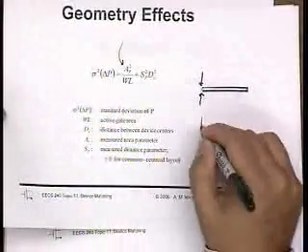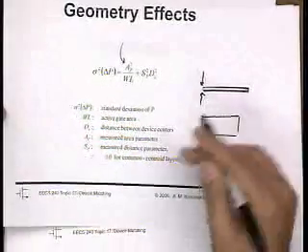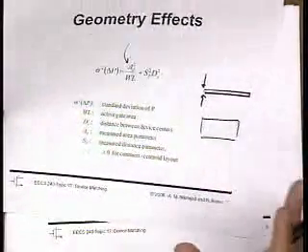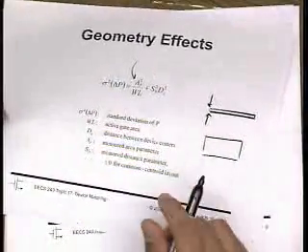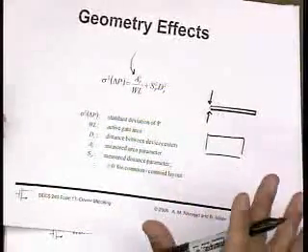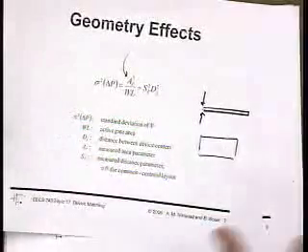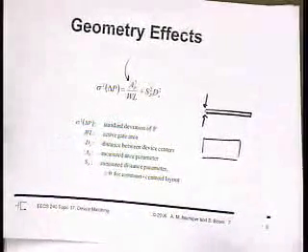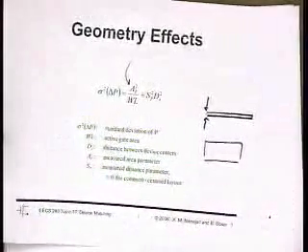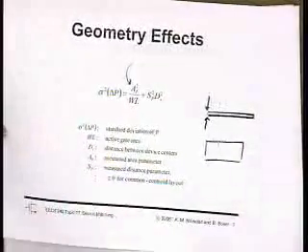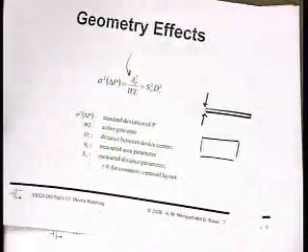The assumption here is that average quantities make sense. If you're talking about a transistor that's so small that a single dopant will make a difference to the threshold voltage, then yeah, this model doesn't work. But usually in analog circuits, we're not dealing with that. In digital circuits, you do lay out minimum size devices. In analog circuits, usually they're big enough, so this is not a concern.